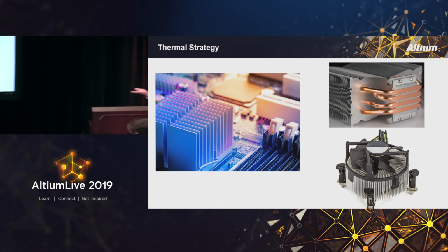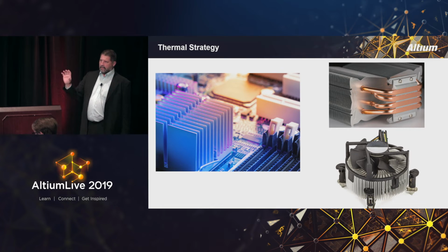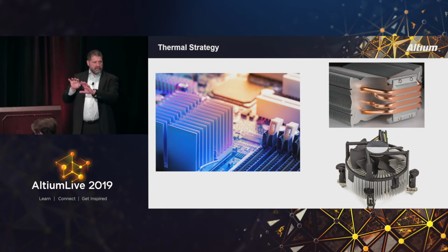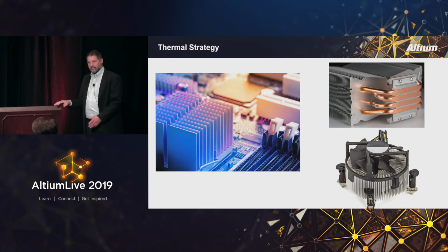Yeah, so it's really important to know the final product mounting. Like, what's the orientation? Is my board flat? Is it vertical? Is it vertical this way? It's really important to know that so that you can arrange the parts so that when the thermal comes off a very hot part, it doesn't have another part baking in that same stream. We want to spread parts away when we do our placement so that we can mitigate that heat, especially if we're doing passive cooling.